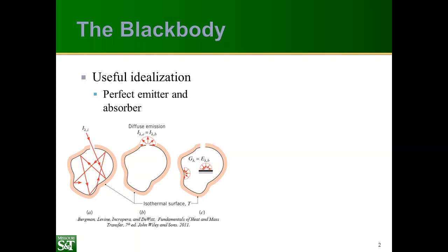It's also important to note that, as in the diagram here, black body radiation exists in a cavity, a large substance with a small opening, regardless of what the surface looks like. The reason is because the radiation gets bounced around all over the place until it's essentially diffuse. And the emissivity behaves as if it was 1 because the radiation leaving every surface is equal to the emission plus the reflection from all the other surfaces. So cavities basically always behave as if they have black body radiation.